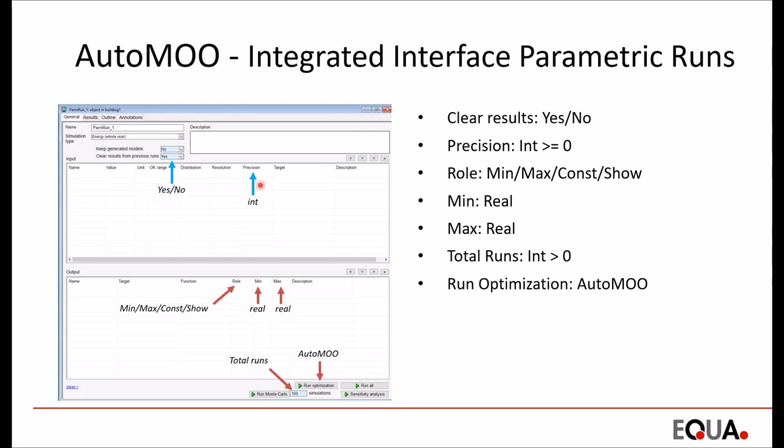And a value of 1 means Automo will treat this parameter as a real with a single digit after the decimal point. Why is this nifty? When should we use this feature? Well, when the physical parameter is limited in real life, think of, for example, currency. In currency, the lowest digit is a cent that we need to consider. Optimizing any further than that is a waste. Or when you would like to narrow a range of a real into a smaller grid size, then that could be beneficial. But beware not to overuse this feature on every parameter, even when you don't need it, because integer type optimizations with large grids are in general harder than smooth real range optimizations.